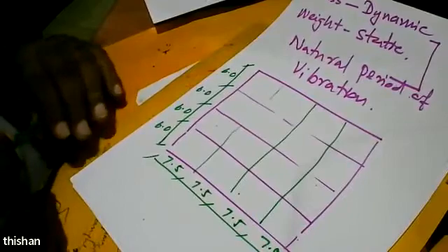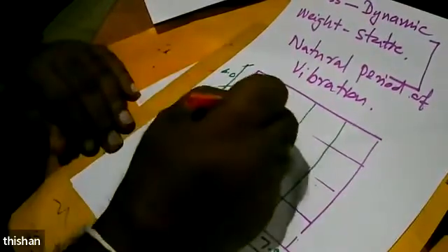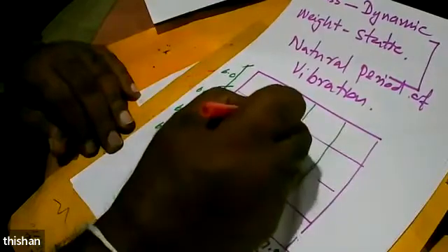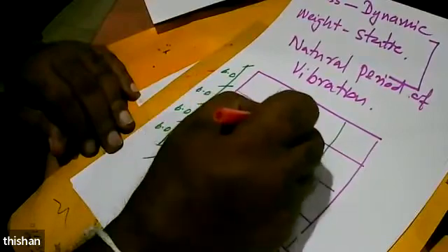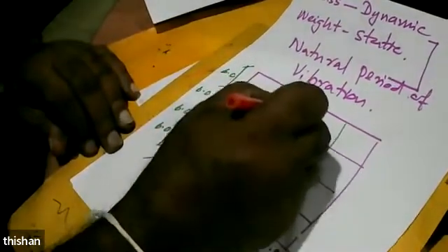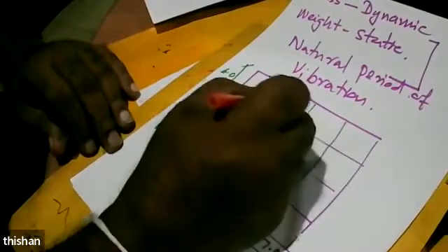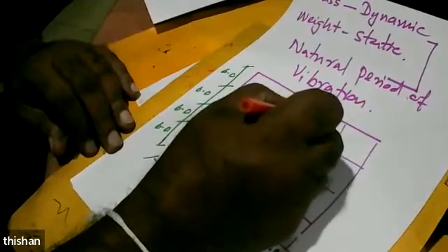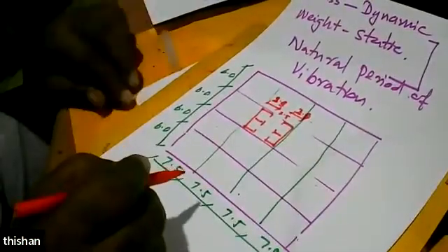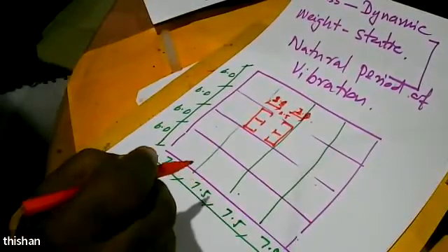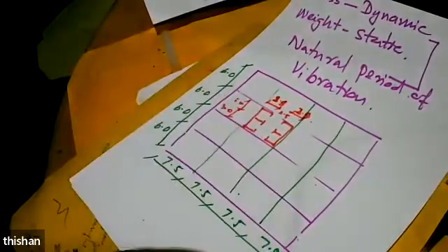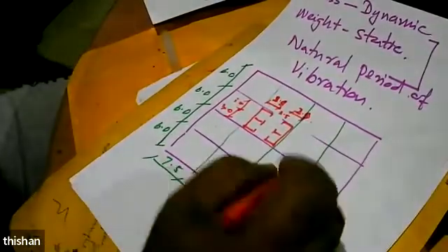When you have a building like this, we need a lift core, and we might have walls like that. A typical dimension for a lift is 3 meters by 3 meters. And you might get, let's say, 2.5 meters, and here we have a gap of 2.5 meters. So we have 2.5, 2.5, 2.5, making 7.5. And we will then have 3 meters and 3 meters. May not be the ideal dimensions, but we consider this as an example.